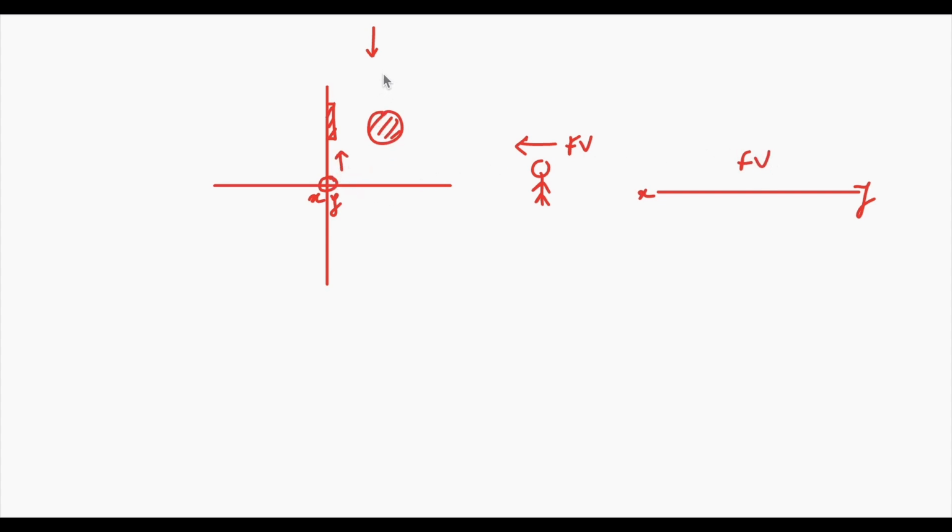When you draw its top view, observing the object from the top direction, its top view will be placed on this horizontal plane which is located below the object. Whenever you get a view on the horizontal plane, you are supposed to rotate that horizontal plane in clockwise direction by 90 degrees. So the view that was appearing over here will be shifted below the XY line, and for that reason, in case of the first quadrant, the front view appears above the XY line and the top view appears below the XY line.